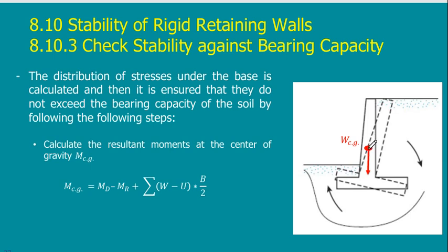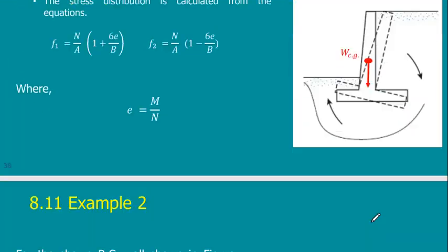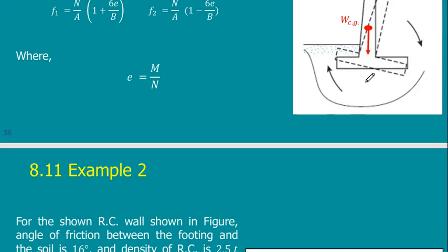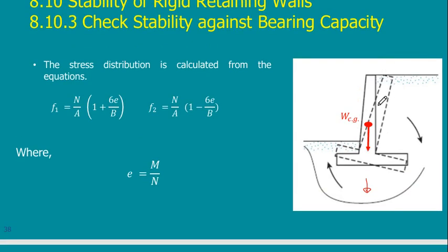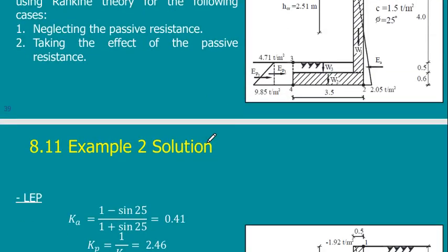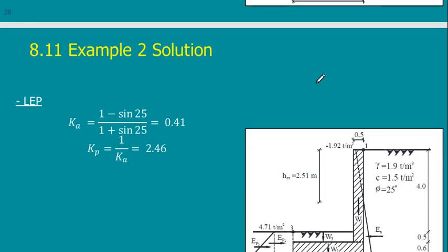But in case I have a little bit of failure due to bearing, what will happen? The wall is going to move down a little bit. Maybe it would move 5 centimeters down, 10 centimeters down. Is there a problem? No, just add another portion to the length of the wall, so this will compensate for the settlement that will happen to the wall. So this is what we have. Check your examples.